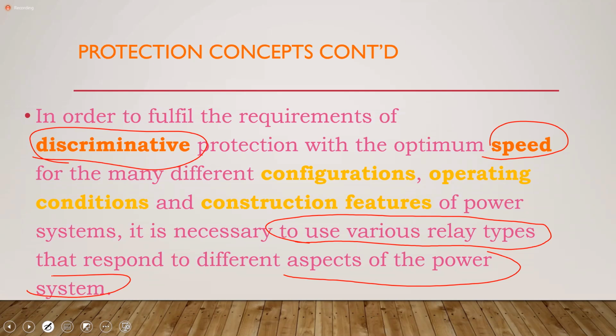Because if there's an issue with the shaft, that shaft running at that high speed, even with a hairline fracture, you will start feeling the vibration. Right? I know that might sound crazy to some persons, because if you have been around a large generator, the place is noisy and, in many instances, always shaking.